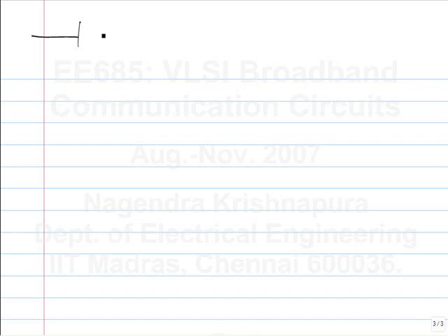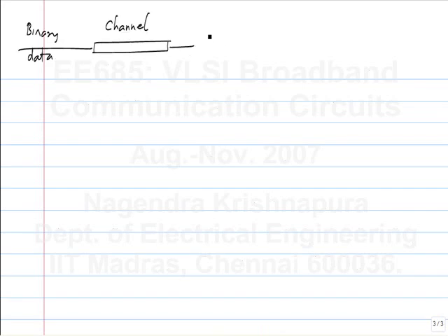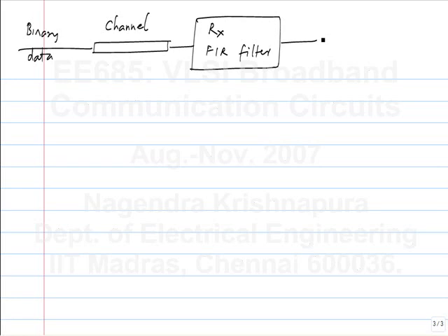Okay, so let's say we have binary data. Okay, this is sent across a channel, and I have the receive FIR filter. Okay, so this has a certain number of coefficients. You can assume whatever number you want. You beforehand determine that this many coefficients are sufficient to cover the range of channels that I am likely to encounter. Obviously, you can't make an equalizer that will equalize any channel completely arbitrarily, but you can choose the approximate number of taps and so on.